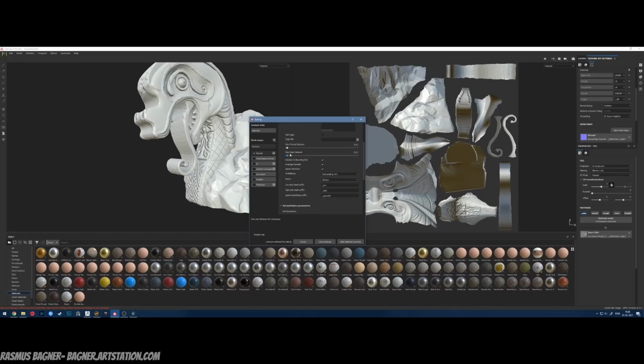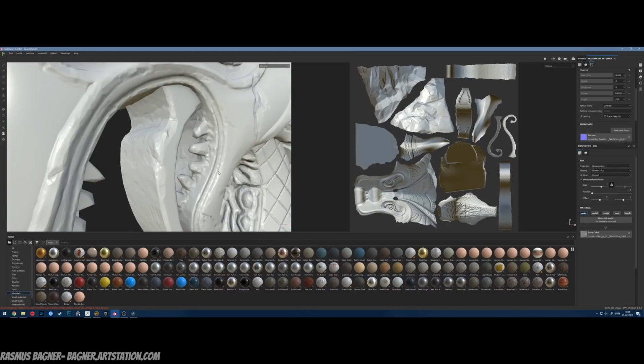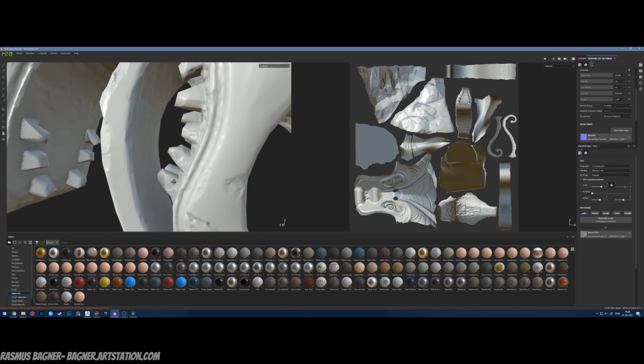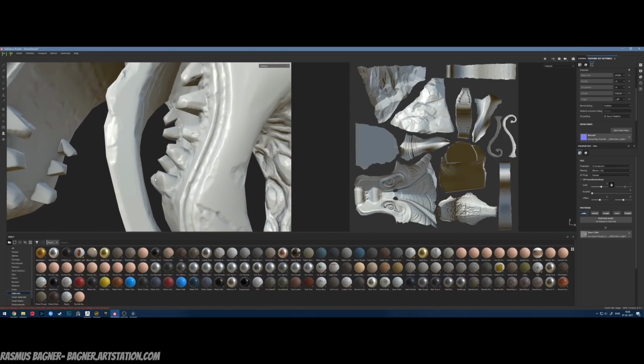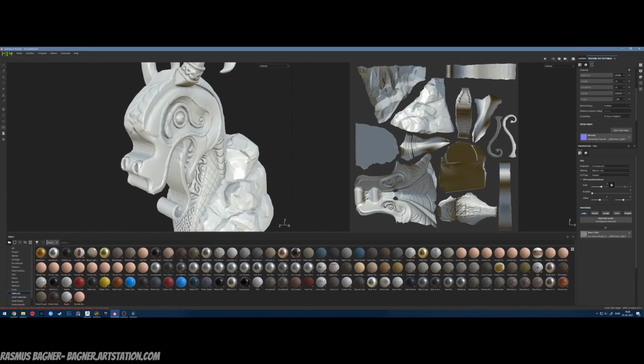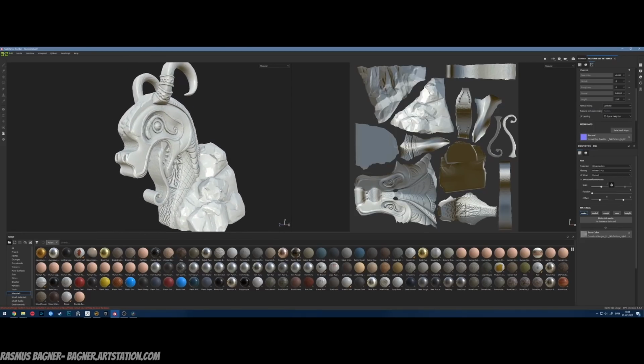For example, down here. Max frontal distance and rear distance is how far out the camera, you could say, goes before it turns around, looks back, and then bakes the normal map from that distance. So if this guy is way too high, for example, in here, it would go out, turn around, but then it would see itself, the actual backside of the tongue. You don't want that. You don't just want it to go out a little bit. That's why you have to make sure the low poly fits the high poly for the most part.